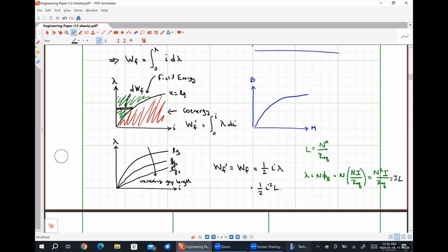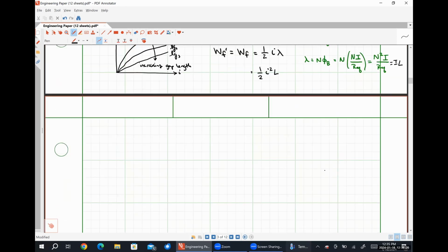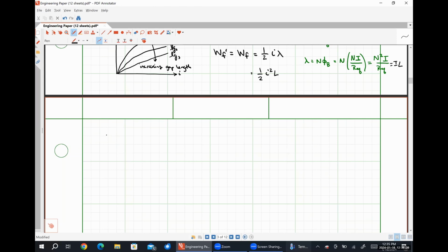So looking at our magnetic circuit, just a couple of relationships that we've dealt with before. We know that our MMF, the number of turns times the current in our winding, is also equal to our magnetic field strength dotted into a differential line element.